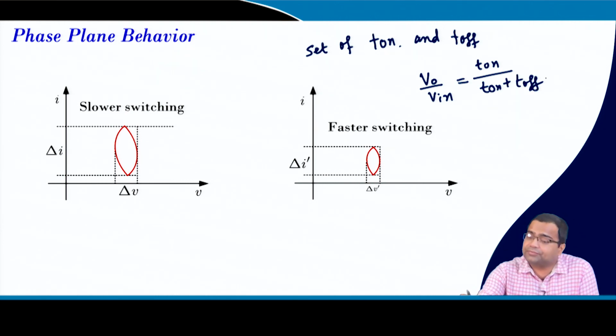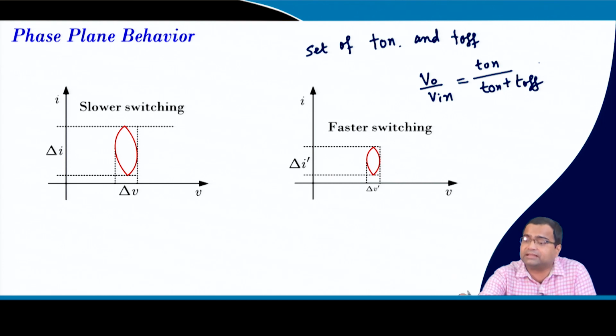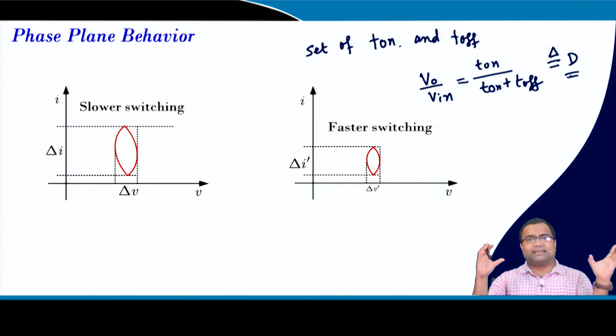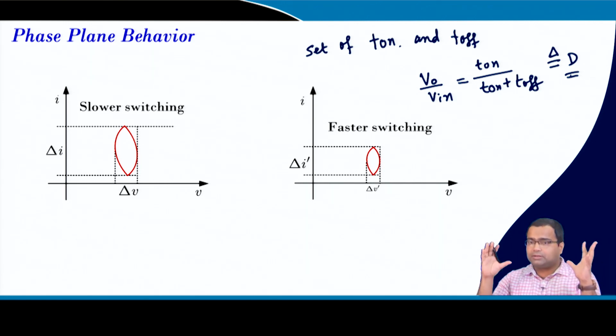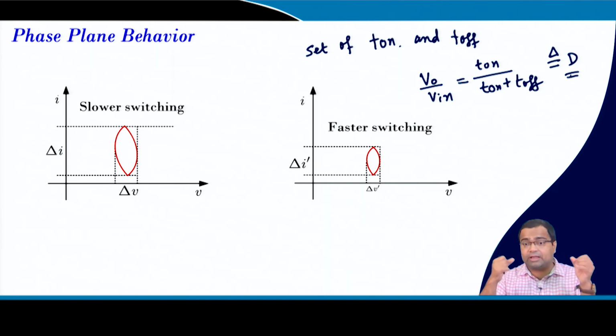Because we are not talking about practical parasitics, this is equivalent to the duty ratio, right? And we have discussed that this ideal duty ratio makes sense for an ideal converter, but in reality converters are practical, and we also know the practical duty ratio is a function of load resistance, then DCR, the equivalent resistance, which consists of DCR plus the RDS on, that we have already discussed.